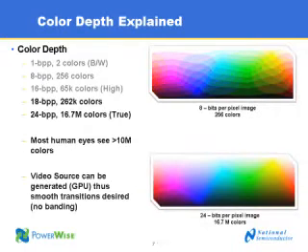All right, so let's dive a little bit into what we mean when we talk about 24-bit color and color depth. This is an illustration. I hope you all can see this clearly on your displays. We're showing the differences between a low color depth and a higher color depth. Just a quick update, if we're talking 1 bit per pixel, then we're talking just a simple black and white display. If we're talking about, for instance, 18 bits per pixel or 24 bits per pixel, we're getting into higher color depth. 18 bits per pixel gives you 262,000 colors, and 24 gives you 16.7 million colors.